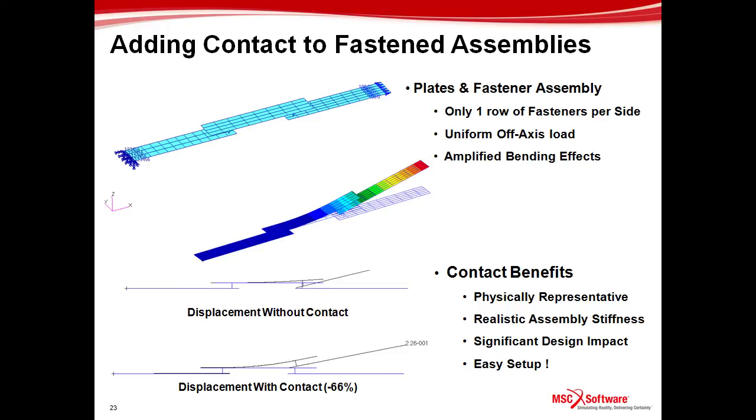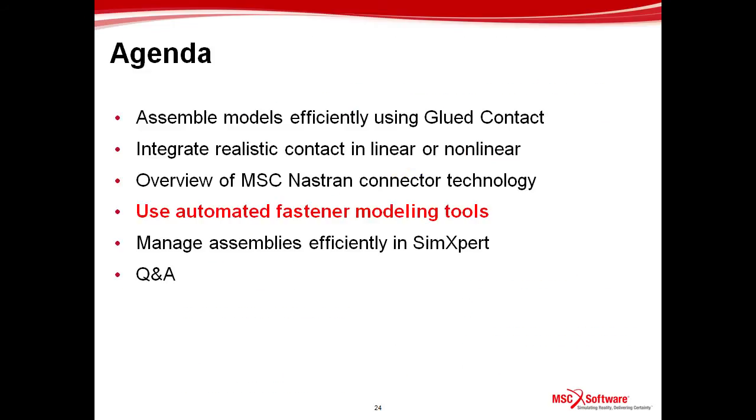So imagine you have complicated assemblies where you have a lot of those locations where flanges are touching adjoining bodies. These little idiosyncrasies add up and will certainly degrade your stiffness. Whereas now you potentially recover the right load path, and potentially also recover the right fastener loads, and if you're lucky, reduce the number of fasteners and do less hand counts without it. So this is great technology because it's easy to set up, it works very well, and it certainly is a benefit to integrate into your simulation practices.